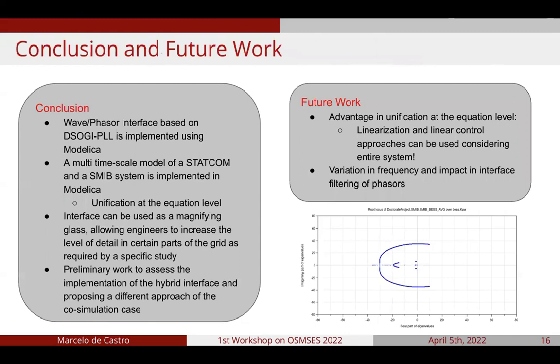As conclusions for this work, we can cite that the implementation of the hybrid interface was successfully done in Modelica, since a multi-timescale model of a STATCOM and an SMIB system was simulated in a Modelica-compliant tool, in this case, Dymola. It is worth noting that the strategy presented here unifies both systems at the equation level, allowing not only simulation, but an integrated analysis. Therefore, the interface can be used as a magnifying glass, allowing us to increase the level of detail in certain parts of the grid as required by particular studies.